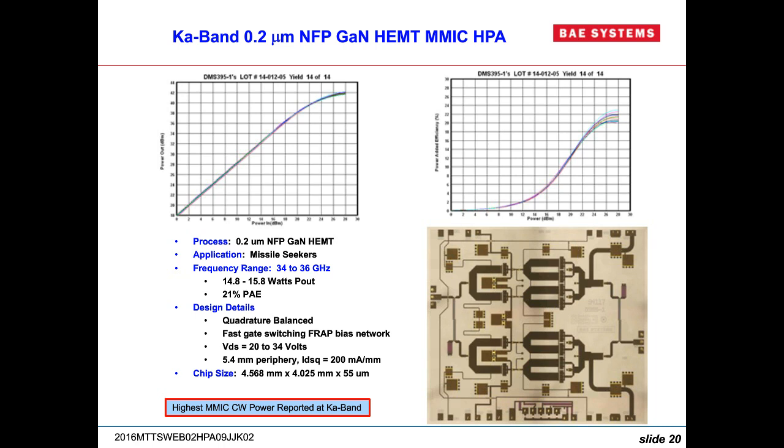Most people nowadays just resort to digital pre-distortion for compensation, no matter what the technology is. One of the reasons is not only the performance improvement attainable in terms of your efficiency distortion compromise, but almost all systems, whether it's radar, comm, or EW today, start or end with digital IQ. And if you've got digital IQ, there's no reason you can't build in a pre-distorted digital IQ transfer function to pre-distort the signal before you feed it to your power amplifier.